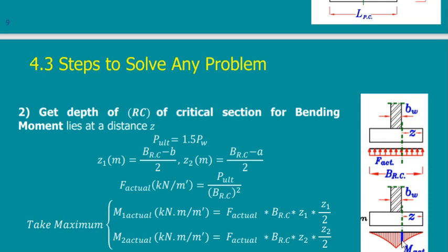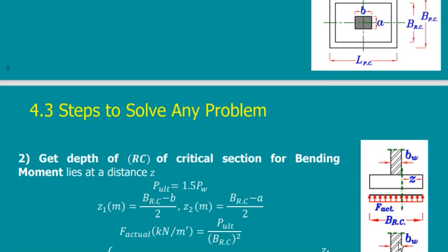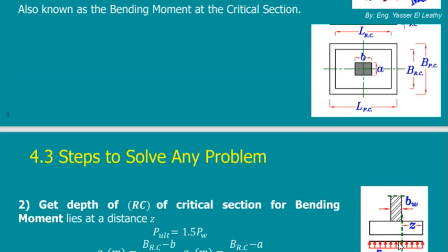It will be a little bit less. Why not take it at the center line? This is the edge of the plain concrete. If I go inside a little bit here, the moment is W times L squared divided by 2. If I go a little bit inside, the moment will increase till it reaches the maximum at the edge of the column. Once you go inside the column, the section has changed. It is not a normal foundation.